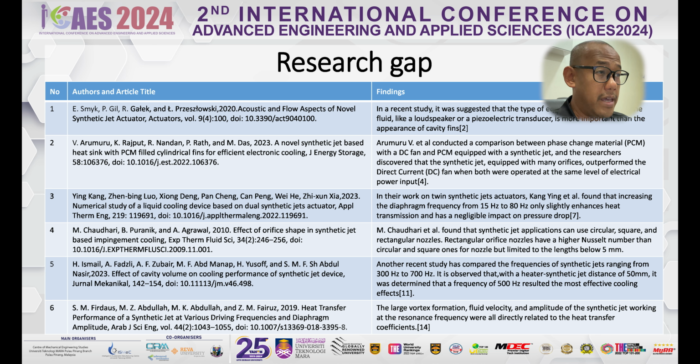It was observed that with a heater to synthetic jet distance of 50 mm, a frequency of 500 Hz resulted in the most effective cooling effect. Another recent study by SM Firdaus and colleagues found that the large vortex formation, fluid velocity, and amplitude of the synthetic jet working at the resonant frequency were all directly related to the heat transfer coefficient.